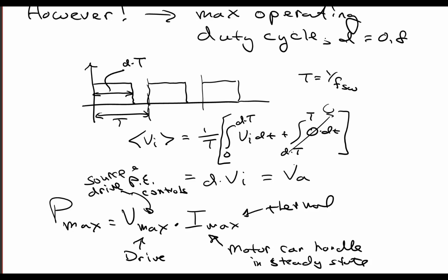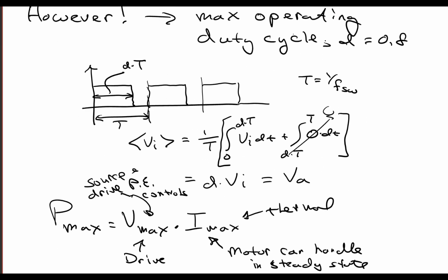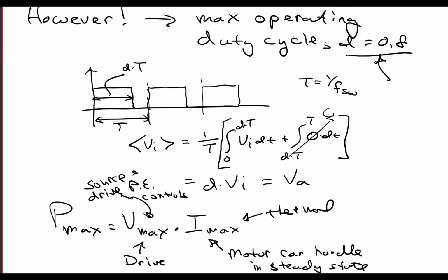So why I said 0.8 is because we're assuming we're operating at steady state of a drive that's actually dynamically going to control up to twice rated speed. So this gives you a margin of control. You could go all the way to 1, but you would completely lose control at D equal 1. And this will become clear as we go into the dynamic things.